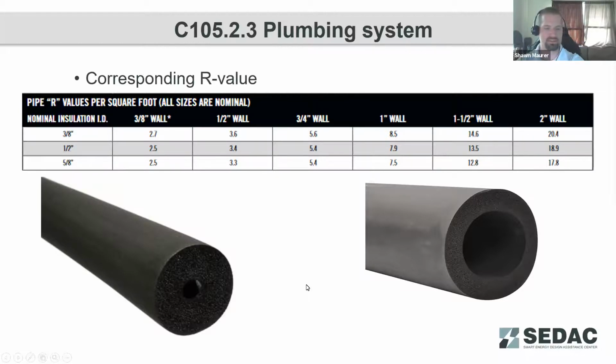Another place where we typically see insulation is near hot water heaters. You've got point of use heaters or large storage tanks. Again, typically we see insulations trimmed away from the tank a little bit. Some people are concerned about that insulation kind of melting due to heat, especially on gas units near exhaust vents. But if properly installed with the proper insulation, that should not be a concern. Also, if the gas systems are properly vented.